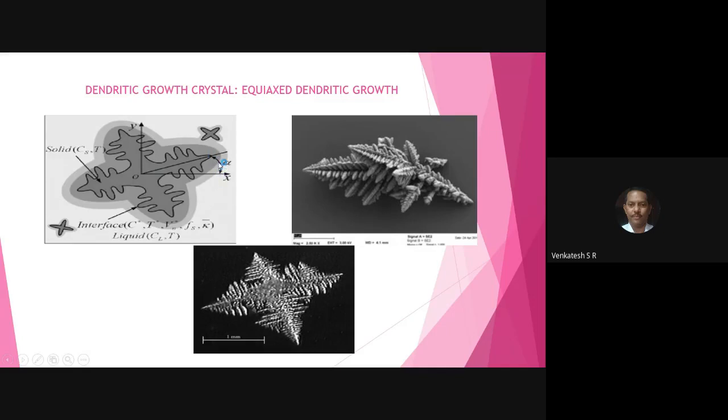In that direction, the crystal grows in size. That is, the nuclei attract the neighbor nuclei, due to the heat transfer between the liquid metal and the bottom of the mold box, between the liquid metal and the mold walls, and between the surface of the liquid and the surroundings.